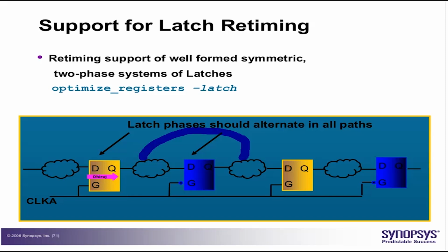In this case, the middle latch should have the opposite polarity compared to the first and last latches. Only then can the time be borrowed. Why? Because a latch, as opposed to a flip-flop, is level triggered. During one phase of the clock it is transparent, and whenever this launches data, it will launch data on the closing edge.